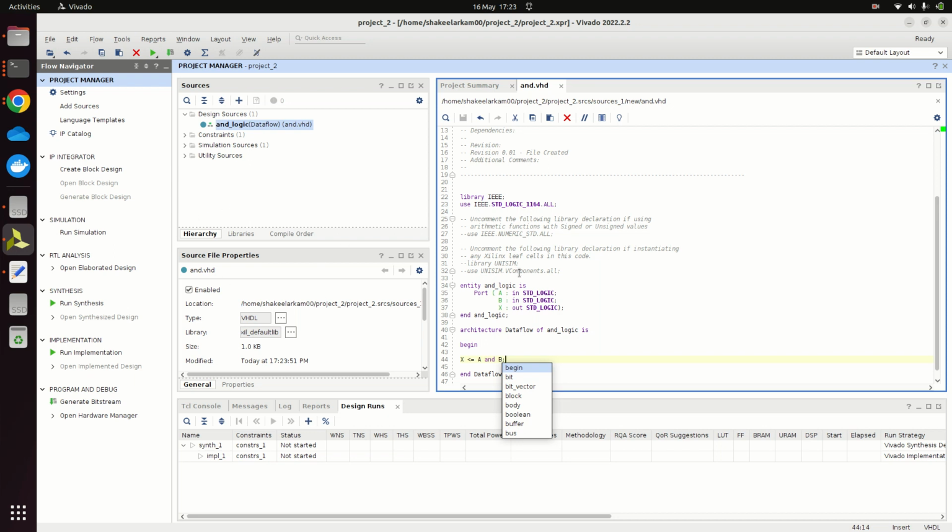So before going to any synthesis, if you see here, this is the run simulation, where you actually test your system to see whether it's working well or not. Then there is the RTL analysis, you see the logic diagram of your gate, and then you synthesize it. After here it's basically the conversion towards the hardware, the HDLs with a bit file. So running a synthesis and then implementing that synthesis and then finally generating a bit file that you are going to put on the hardware.